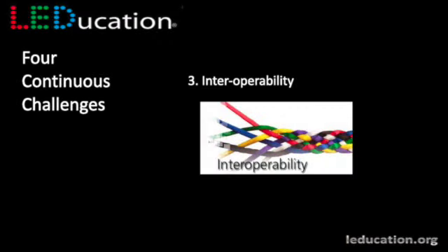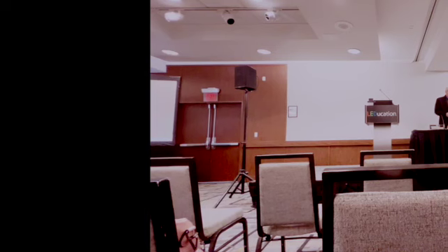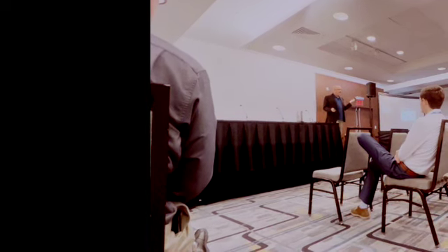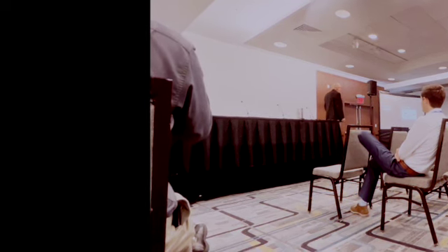Interoperability. People challenge me on this sometimes, but the fact that these systems do not talk to each other. I'm not talking about lighting systems talking to HVAC. That's a challenge in itself, but we can bridge that by going through BACnet and things like that. I'm talking about if you buy a RAB LightCloud network lighting system and you put it up in the ceiling, and then you buy a different set of fixtures not made by RAB, you've got no way to control them because whatever system they're selling is not going to work on the system you've got. Or, if for some reason LightCloud is no longer supported by RAB, now you've got a broken building. Right? This has already happened with Redwood Systems, where people put all these Redwood lighting control systems into their buildings and Redwood went out of business. So that's number 3.